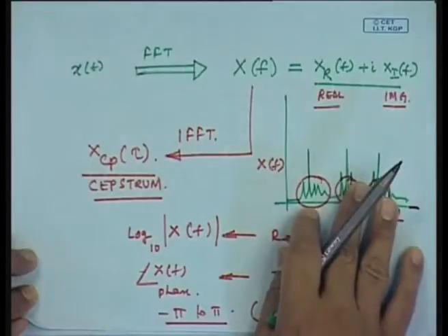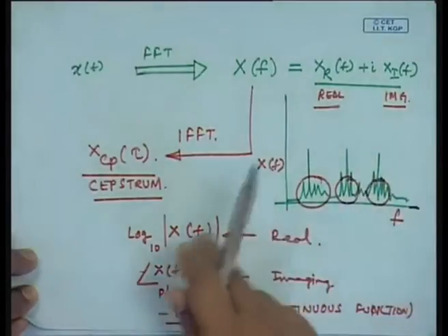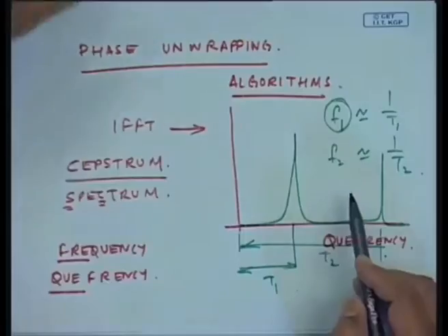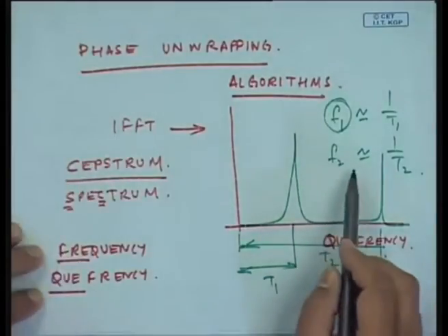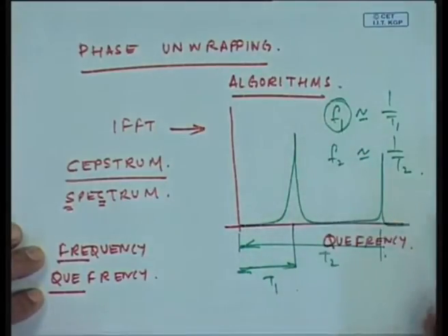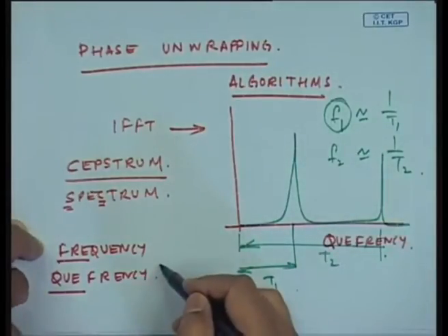Because FFT analysis, in our class, we have seen with a nice pure tone and nice mathematical functions, we get neat Fourier transforms. But in reality, once you go to the machines, we will have so many unknown frequencies, it becomes very difficult for us to find out which frequencies are present, which are the defect frequencies and so on. So, if I do this Cepstrum, I can find out whether F1 is strong enough or F2 is strong enough or F3 is strong enough or so on, depending on as many Q frequencies you have.